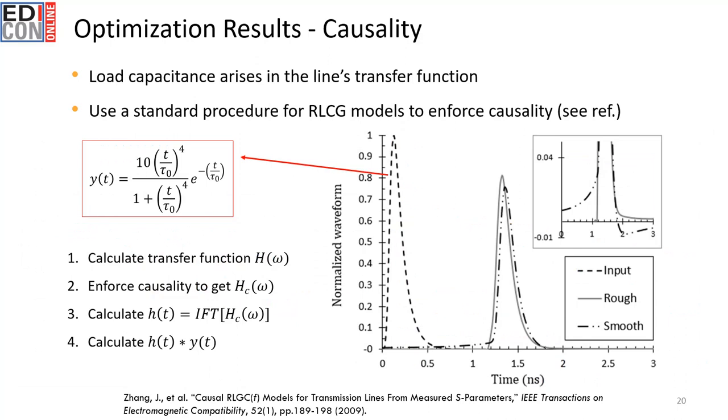Now, once you have all of this, you can then do your tests for causality, and you can calculate the impulse response. The impulse response that I've shown here is using the input impulse that's defined in IEEE 802.3 standards that's used for testing Ethernet channels. But you could use any other impulse you like.